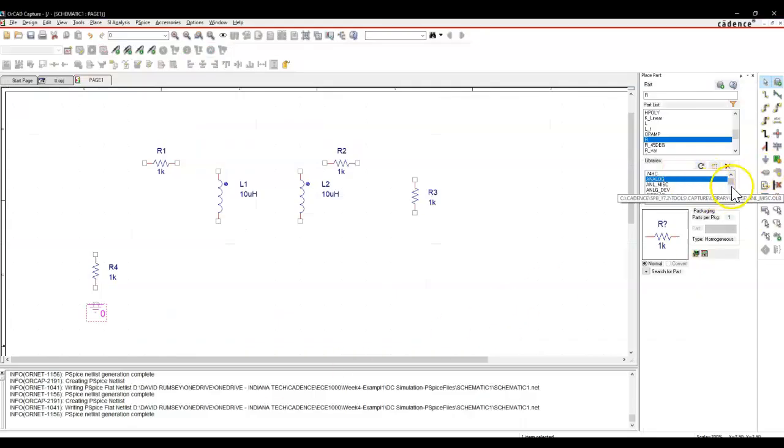So if you go to your sources, and you say, okay, well, let's just go to voltage. Oh, look, there's this AC voltage here. Oh, I just want to apply that. Wrong. That AC voltage is really used for frequency analysis. And we're not doing any kind of frequency analysis. We are actually trying to still do time domain. So that VAC is not the one we want to do.